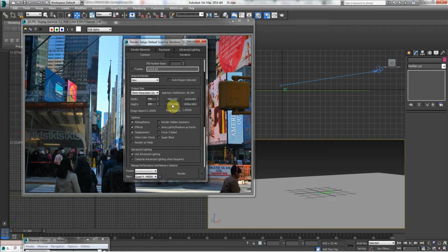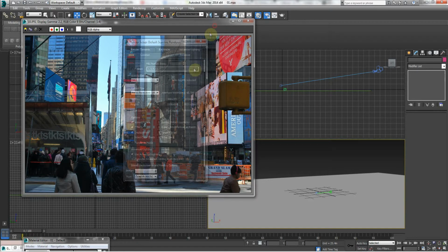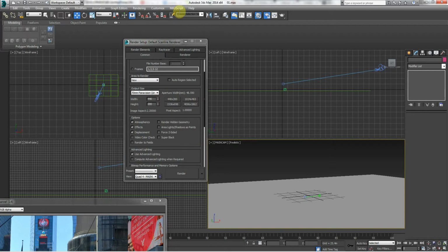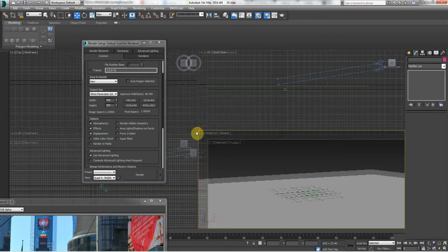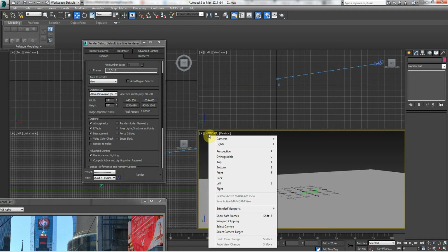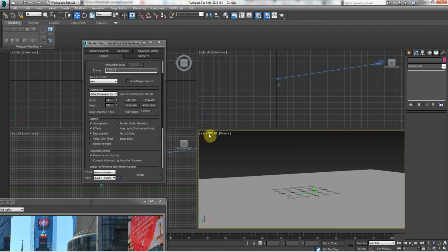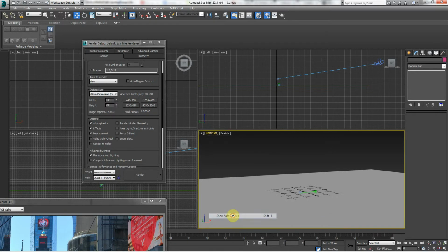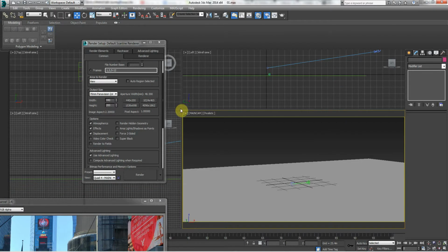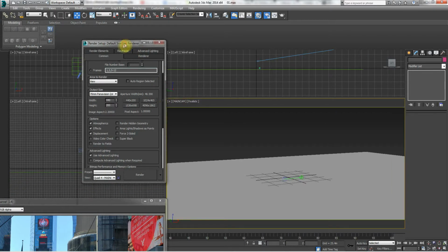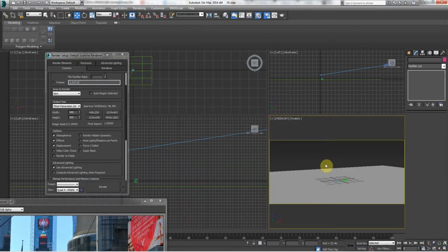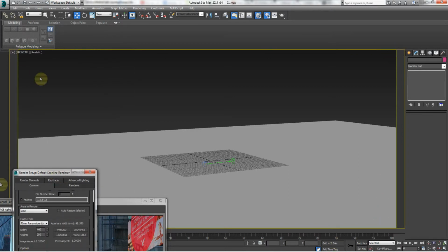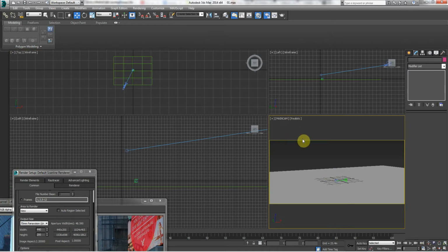But in this viewport, it hasn't changed the dimensions yet. That's because the dimensions are still the viewport's. So what you want to do is right-click on your main cam name here, and go to Show Safe Frames. Click on that, and immediately you'll see that the dimension of the Panavision view is kept. So this yellow line around here is the Panavision dimension. So you'll see exactly what the composition will look like in the viewport now.